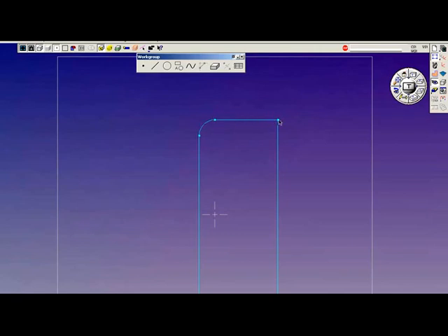In this corner, I want a chamfer. I pick the point, chamfer tile, chamfer along the side. I'm going to leave the value at 0.5 to illustrate how the distance changes. 0.5 along the side. There's our chamfer. It's 0.5 from this imaginary point to here, from here to here. Chamfer in this corner. This time defined along its depth. Same value. Notice how much larger it is.